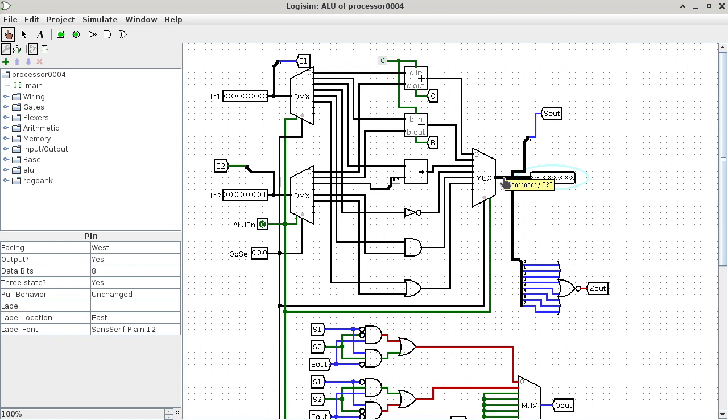Okay, so the ALU is just a bunch of operations. You can look at it as a menu of things it can do: these are the inputs, I want you to do this to the inputs, and give me the result as the output. That's all it does. But it cannot remember anything. It can do the calculation, but after a while, if you present new input to the whole thing, it completely forgets about the old output, and it will try to redo the calculation.